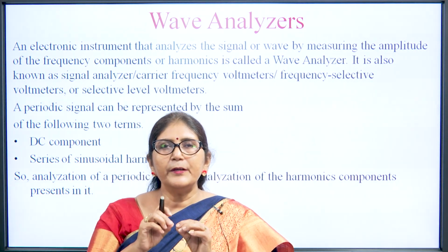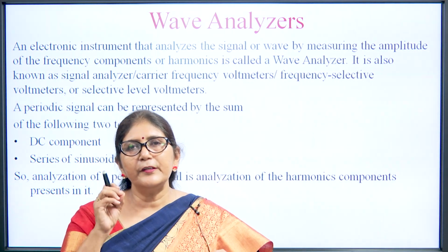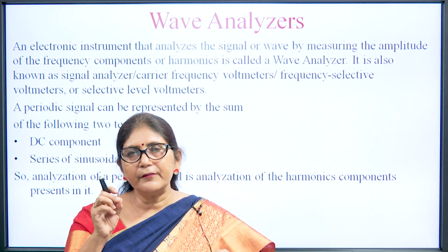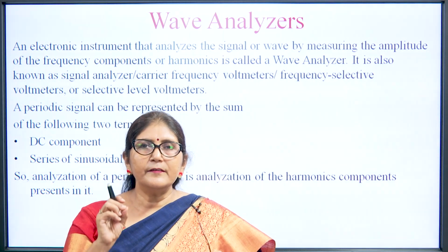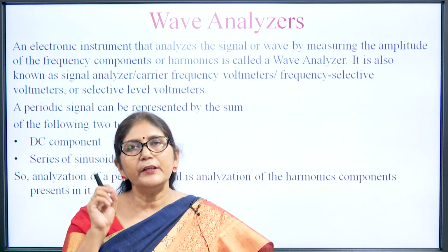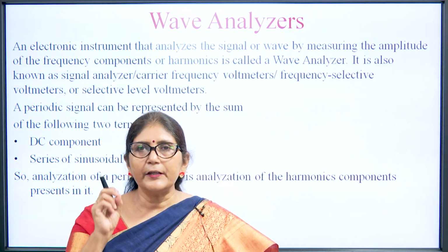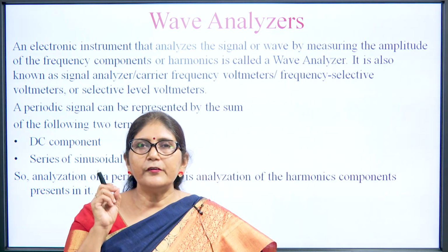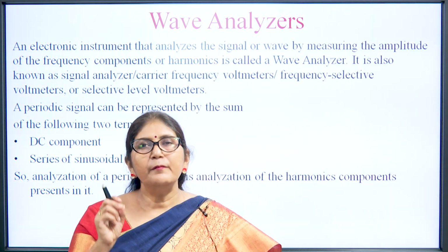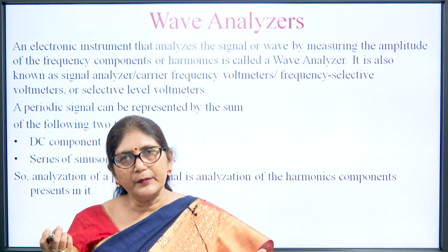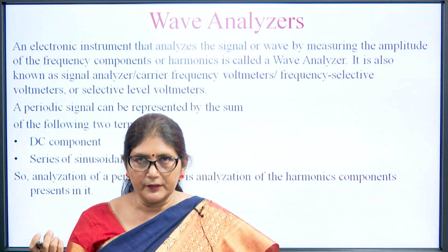So, suppose we want to measure the fundamental frequency component, then we can select that particular frequency. There is a knob, by which we select the particular frequency and it will measure the amplitude of that frequency either in terms of dB or in terms of simple voltage.